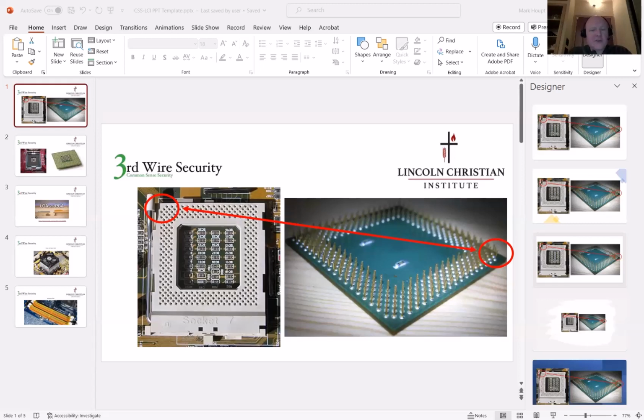Your LGA is very similar. There's going to be a lever or a series of levers that you have to open up, probably a cage, if you will, that will be on top of where the LGA chip card goes for the CPU. You'll lay it in there. Usually the LGAs will have arrows printed on the circuit board itself and also printed on the socket or the motherboard.